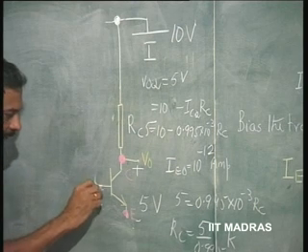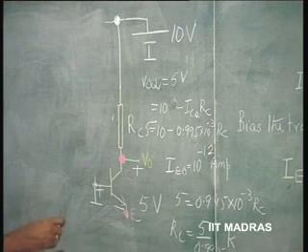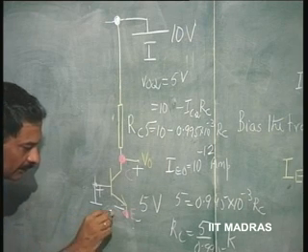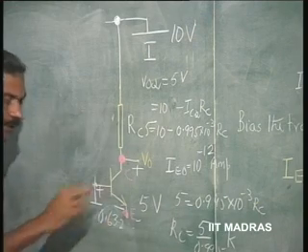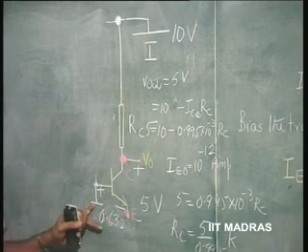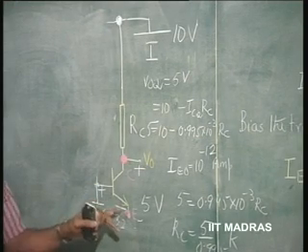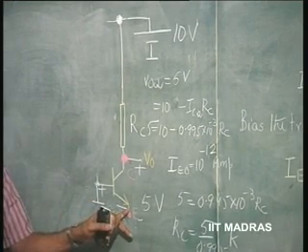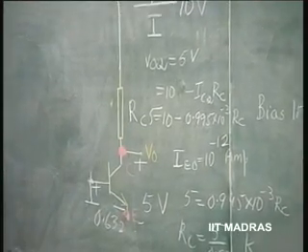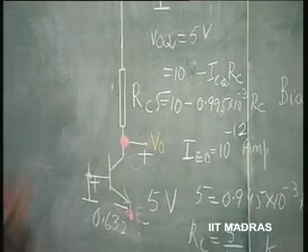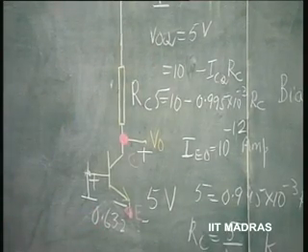Then that will fix the current in the emitter. This voltage we have already fixed as 0.632, but now it is negative. So, if I ground this base, connect it to ground, make that common, and apply a negative voltage of 0.632 to the emitter, then again it is biased according to what we require. But again, getting 0.632 negative voltage is very difficult.